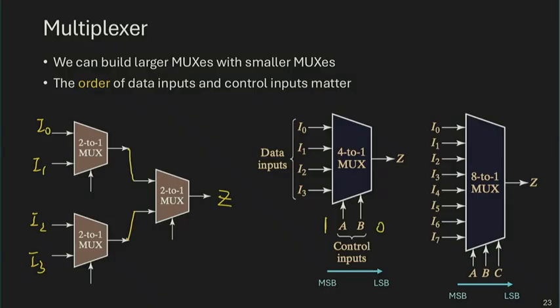So what do I do? Well, I want to activate essentially this path if my AB input is 1 and 0. And by the look of it, this signal is connected to the 1 side of the 2-to-1 mux. This signal is connected to the 0 side of the 2-to-1 mux. So I can put down the B variable over here, A variable over here, to make the selection.